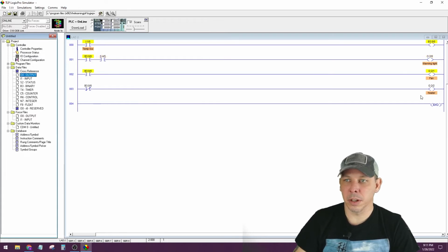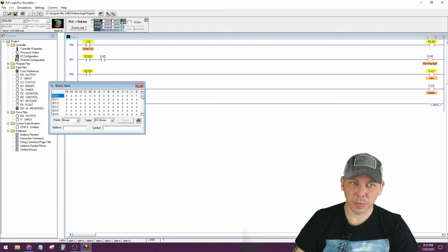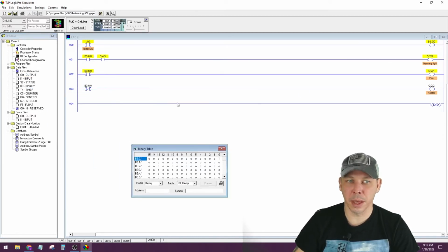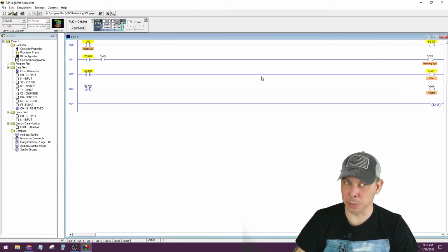The reason that you don't want to do that on something like the small MicroLogix is, some of those only have 6 outputs. So if you use actual outputs to do this kind of relay thing, if you do that like twice, you took a third of your possible actual outlets up, and then you can only have like 4 things that are actually connected to it that are being controlled. But you have a ton of internal bits that function the same as a relay coil, and then you can make unlimited amount of contacts associated with that, and some of them can be normally closed, some of them can be normally open. It doesn't matter.